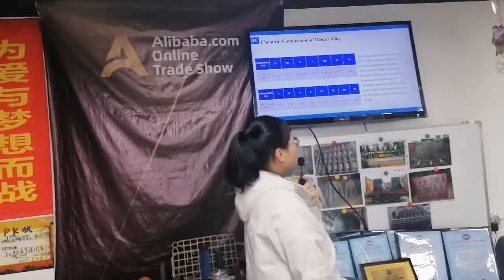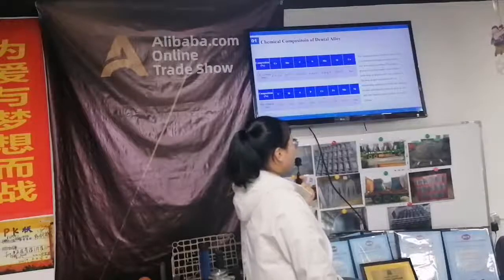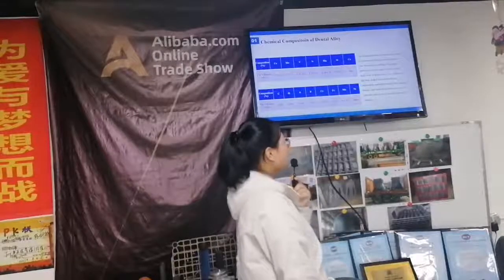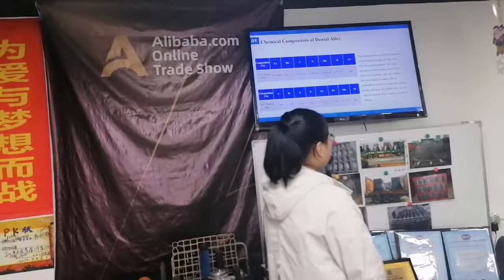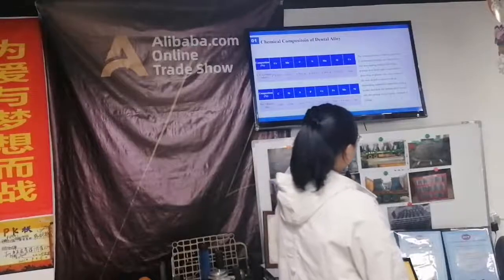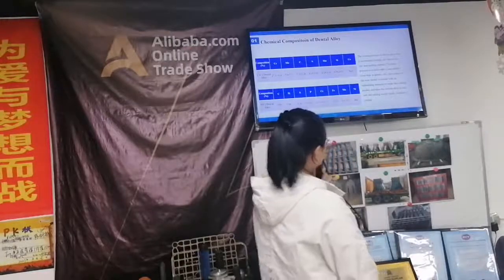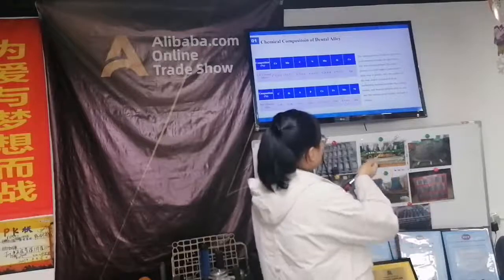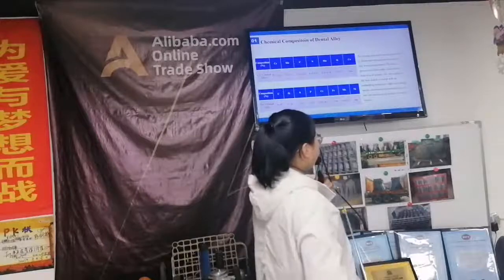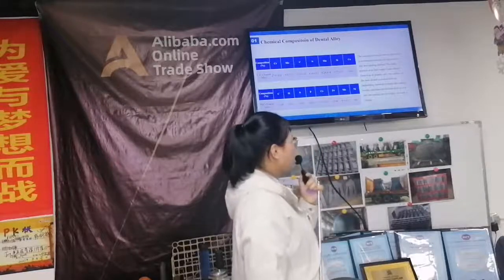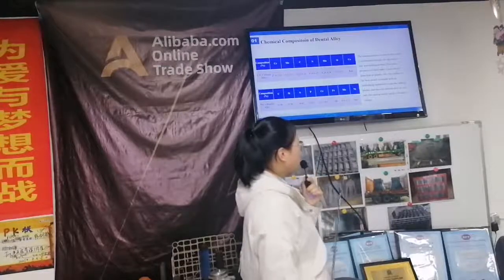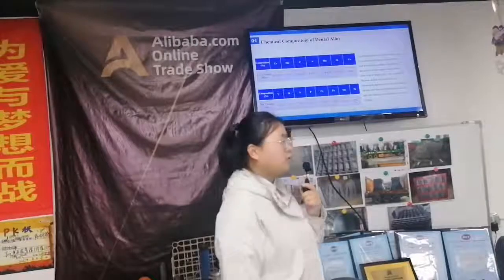The casting process of dental alloy parts is investment casting, also known as wax casting method. The basic process is to first make a wax model from wax or plastic. The surface of the wax model is coated with an investment material to make the casting mold, and then the molten alloy is cast into the casting cavity inside, forming a casting.